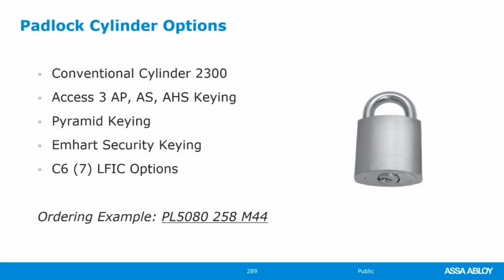The answer, it was kind of a trick question. I said, can you use a deadlock on a fire-rated door? And we had a no, and we had some yeses. The answer is you can use a deadlock as an auxiliary lock as long as you have a fire-rated latch mechanism as the main source of latching. The deadlock is considered an auxiliary lock. There are also egress reasons you'd have to check as well. On doors in a means of egress, you couldn't have that lock on because that would require 2 different motions to get out. So yes, you could theoretically use it in a fire-rated door as long as it's not in a means of egress and as long as it's not the main latching mechanism. Thank you guys for your participation.